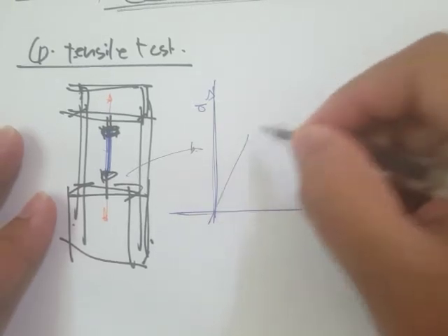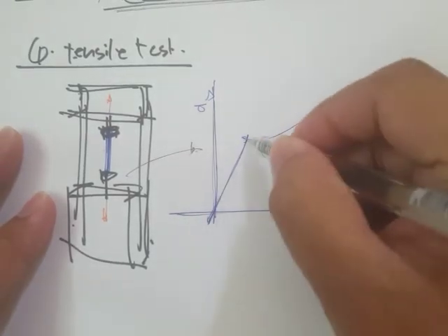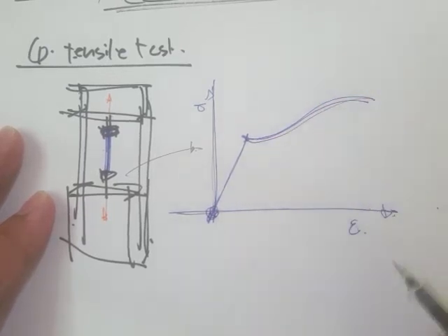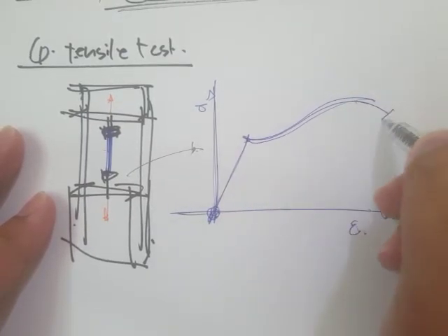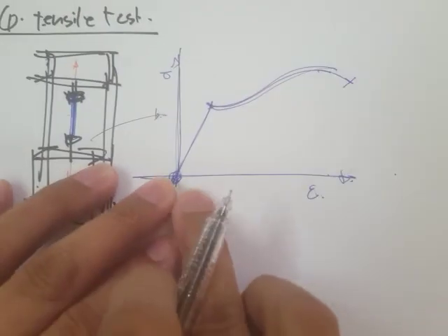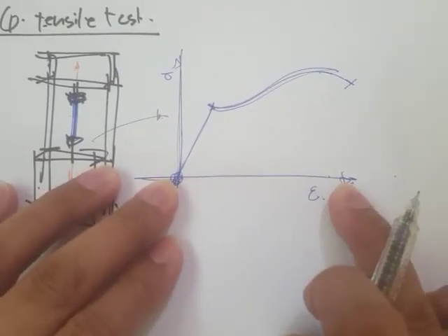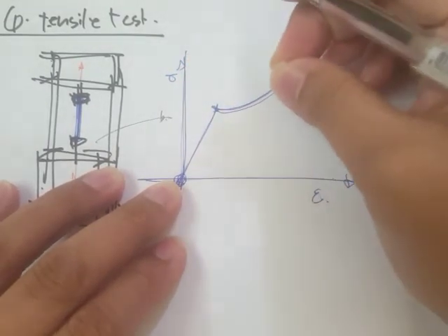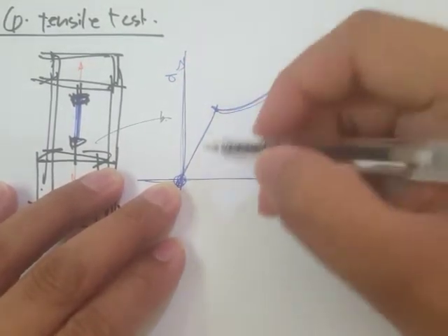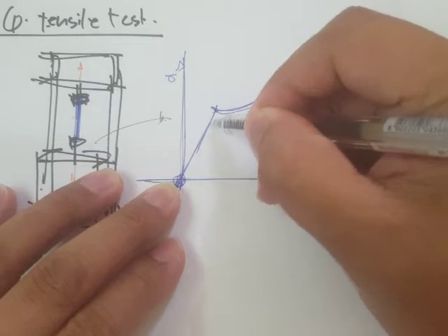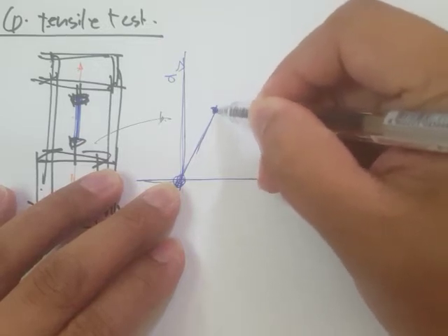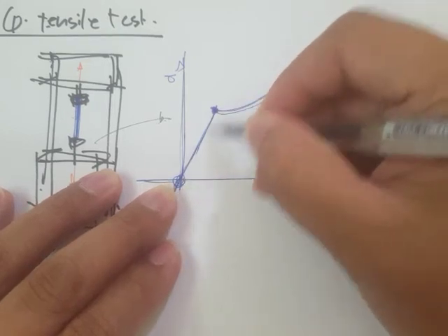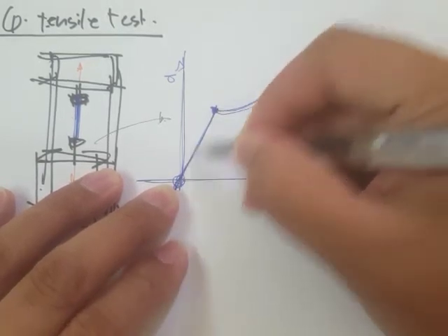One example is steel. It has this stress strain curve diagram, and it records, if here is the strain along the horizontal axis, and here is the stress along the vertical axis. When you apply loads and increase the loads, there will come a point where it's no longer linear, because right here we have a linear proportion.